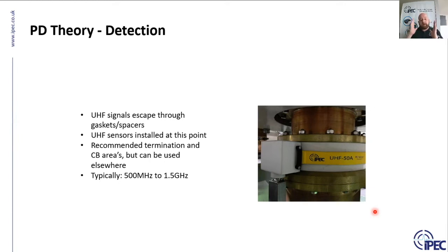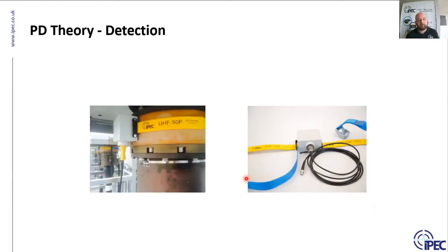Quite often, there's lots of different barriers around the equipment, so quite often we install them where the customers have the main concern. Sometimes the main concern is in the CT or the VT or the circuit breaker. It depends on the switchgear, and on the history of failures of that type of switchgear. Quite often it's also on the cable termination. Cable terminations are naturally a weak point in any equipment. I think this picture here is a cable termination, so the sensor is installed on the barrier of the cable termination there.